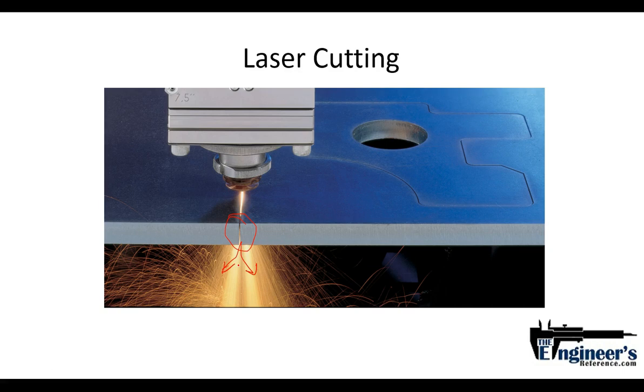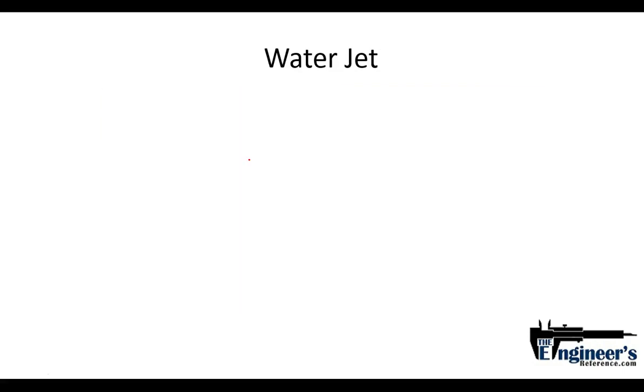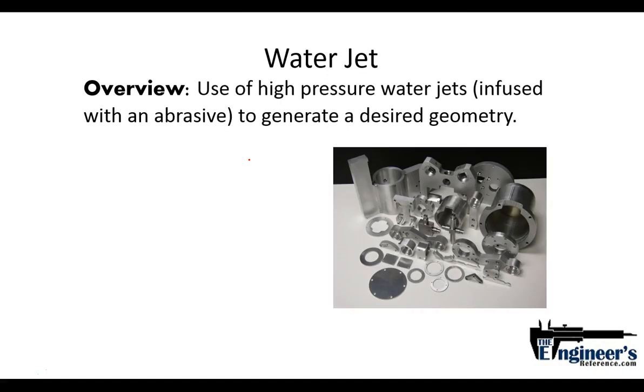Now this is showing a 2D component. It is possible to have 3D features where the head is actually on a knuckle and able to rotate, but again, that's an extremely expensive addition to your components. Now waterjet, that's something that we have looked at in your project. I think the process layout actually shows that you're outsourcing for your component that you're redesigning and applying your DFMA principles to. So just a little more depth into it.